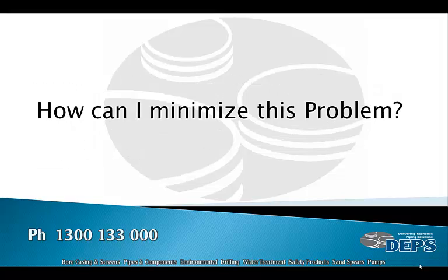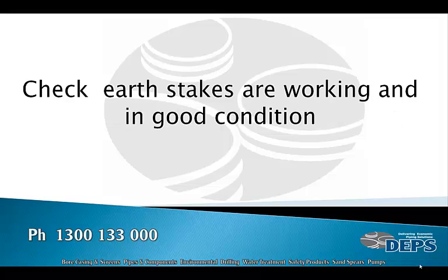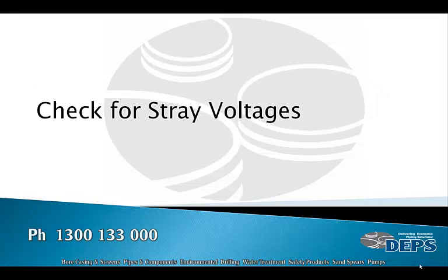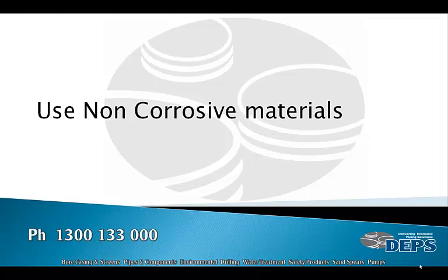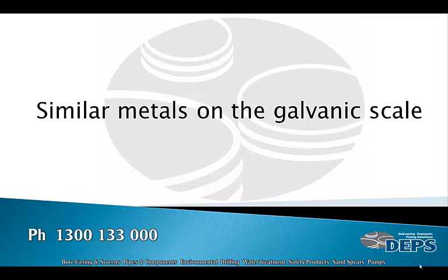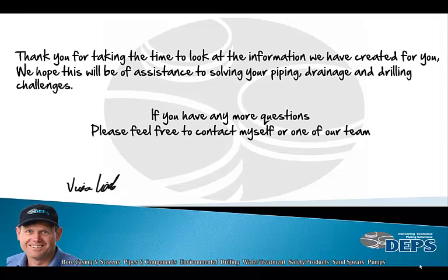How can I minimize this problem? Check earth stakes are working and in good order. Check for stray voltages, AC and DC. Neutralize water conditions. Use non-corrosive metals, similar metals on the galvanic scale.